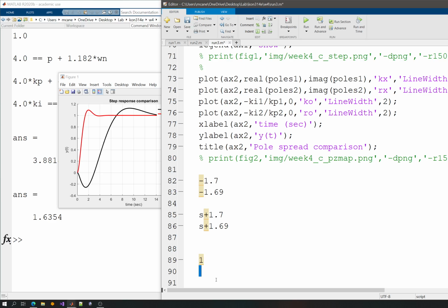You can just design a heater slash cooler that is guessing the room temperature. That's not that ideal, because you do not check the physical quantity there. You have to check the room temperature, and if your reference is different, then you will act on that. You will cool or you will heat the room.